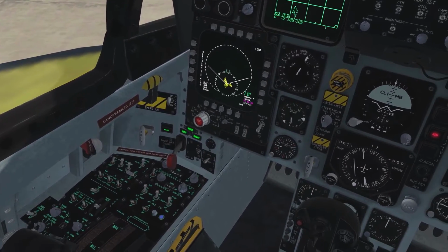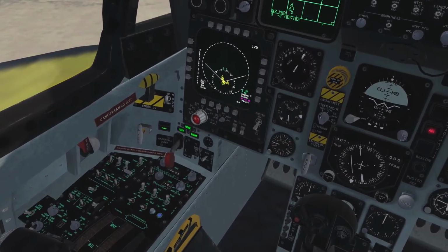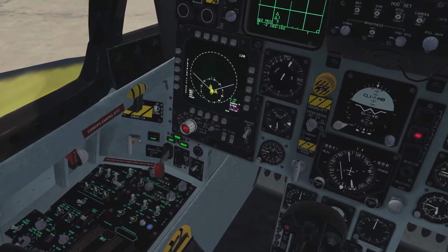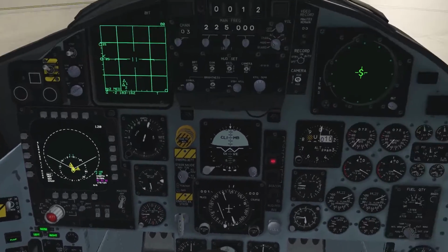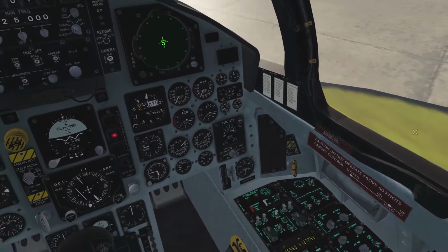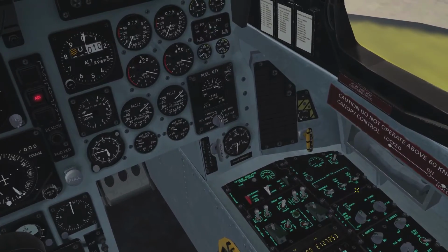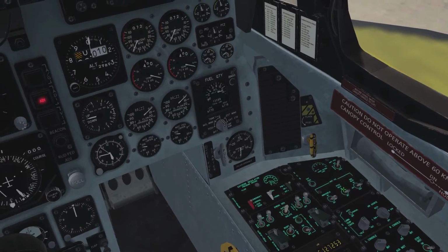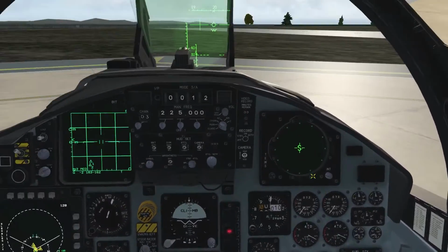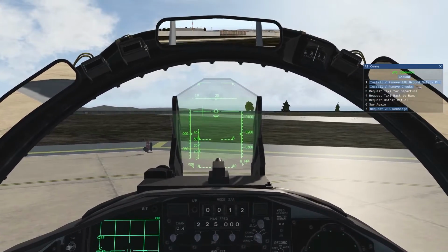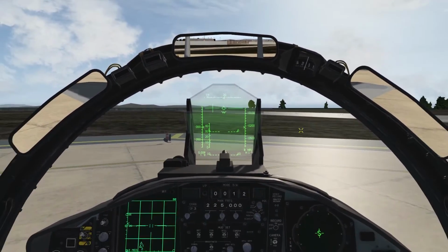So this is where I recommend pressing your trim reset button, just to ensure that you haven't inadvertently entered some trim input. Checklist mentions if the aircraft is manually trimmed nose down from takeoff trim, nose wheel liftoff speed may be increased. Then next point on the before takeoff checklist is to confirm the canopy is closed and locked, which we have here. Pitot heat is on. We've got a click spot for it, but the switch is non-functioning. Warning, caution, bit lights, and circuit breakers. So the warning, caution lights we can check all out. We're good to go. So we'll get our takeoff clearance, and we'll execute a normal takeoff.